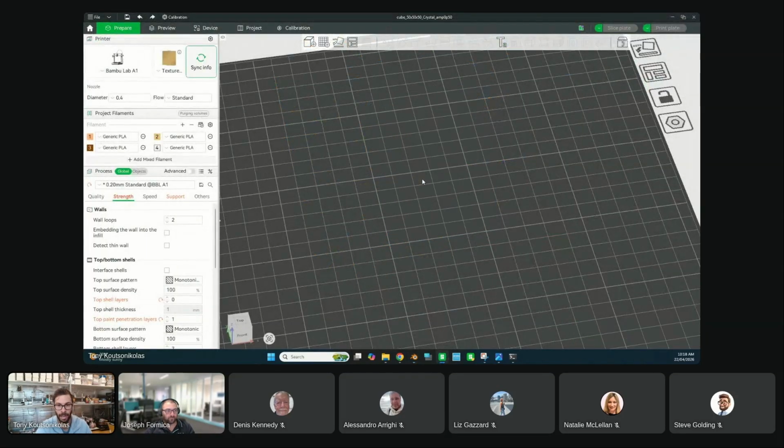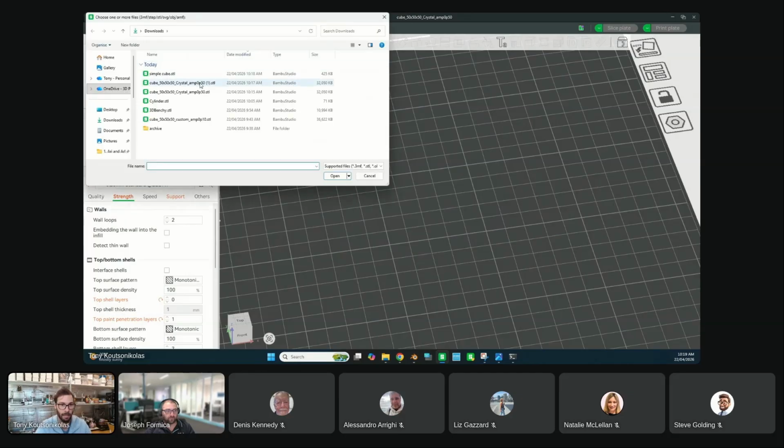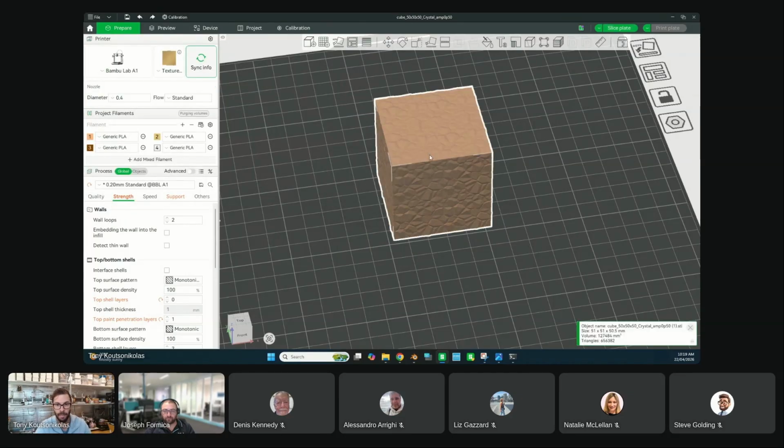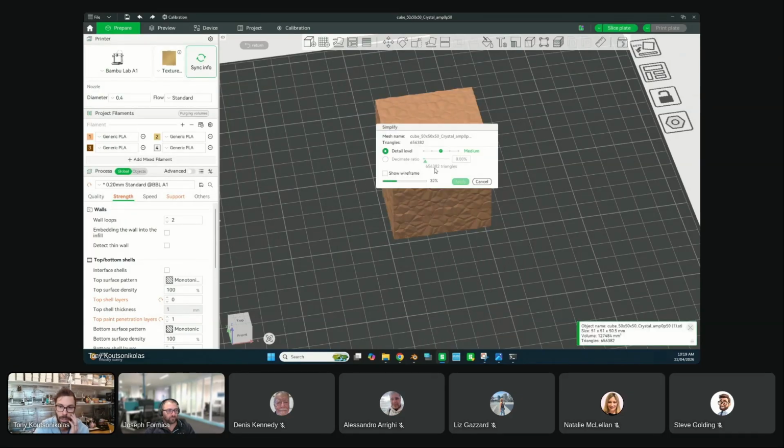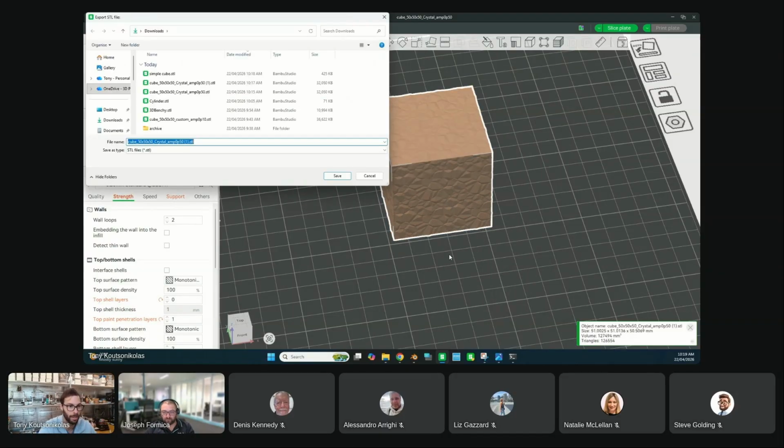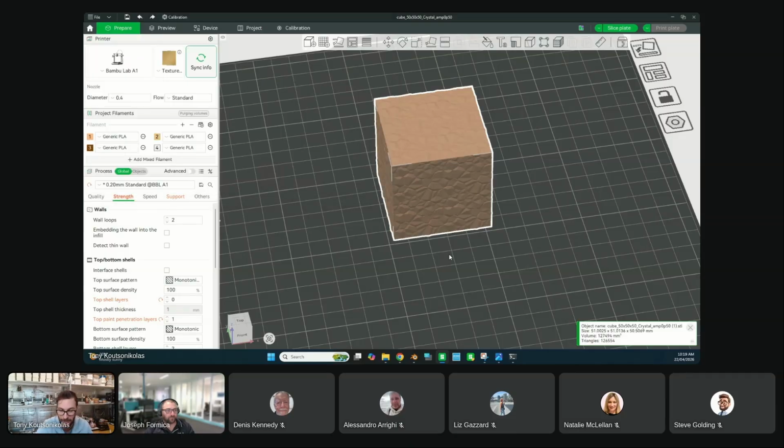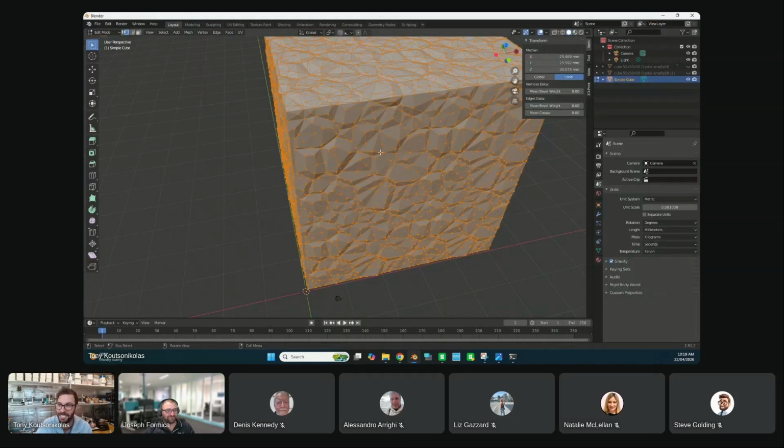And that is where I could delete that, put my original one back in, and then go Simplify Model, and instead of detail level being on medium, maybe I put it on high. You can see that it's still reduced it quite a lot, like by 92%, or even if I put very high, it's still reduced quite a lot. Then I can hit apply, export. So this is high detail reduction. I'm going to come up with better names here. High detail reduction. Yeah, that makes sense.